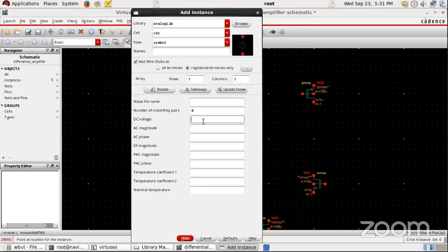Yes sir, I have a query. Since it is PMOS, that's why the width is 30 micrometer? Otherwise it would be identical to the NMOS; if it were NMOS, then the width would be 10 micrometer, right? You can decide. All the four transistors should have the same aspect ratio if they are the same type. Not necessarily.